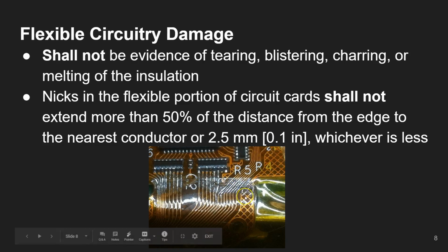You should keep in mind that mechanically created indentations caused by contact between the cover layer and molten solder are not rejectable. Care should be taken to avoid flexing conductors during inspection.